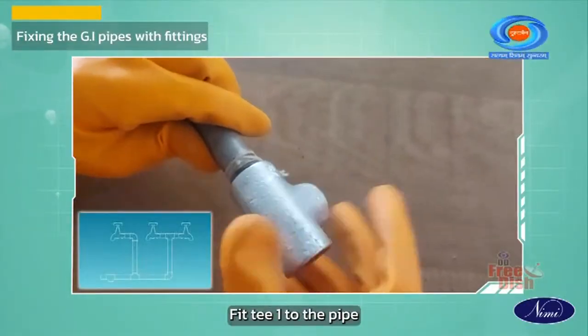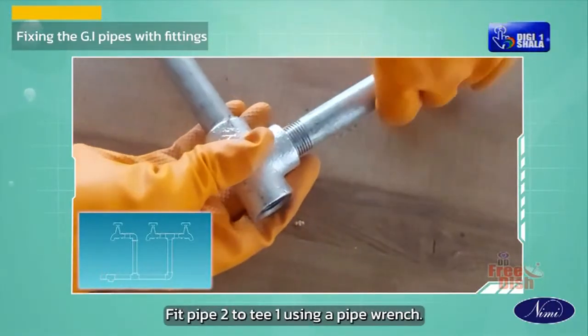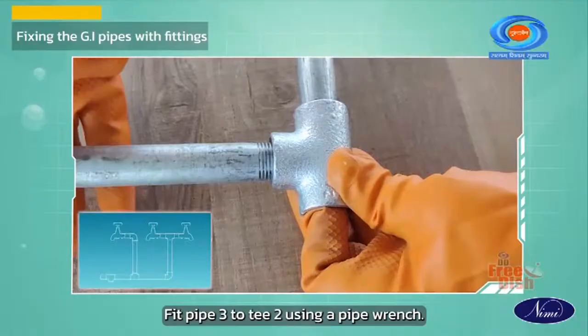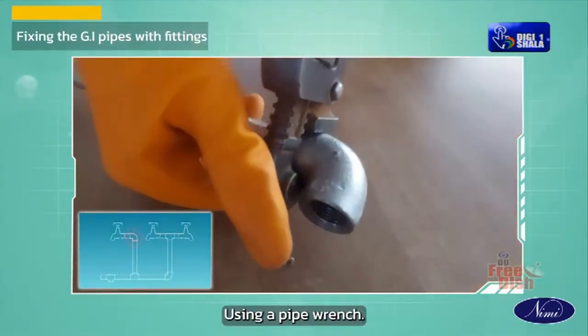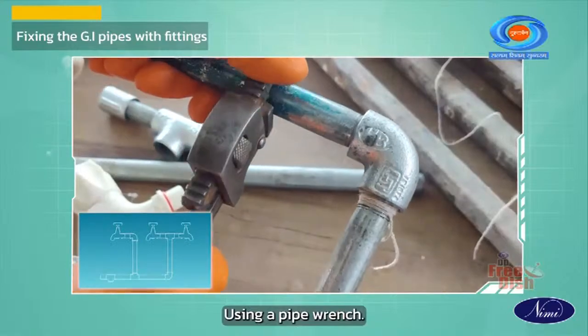Fit T1 to the pipe 1 using a pipe wrench. Fit pipe 2 to T1 using a pipe wrench. Fit T2 to pipe 2 using a pipe wrench. Fit pipe 3 to T2 using a pipe wrench. Fit elbow to pipe 3 using a pipe wrench. Fit pipe 4 to the elbow using a pipe wrench.